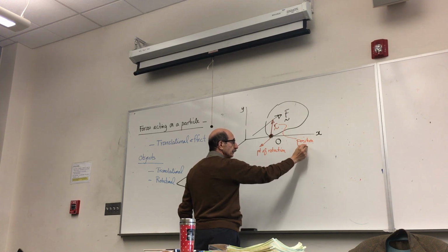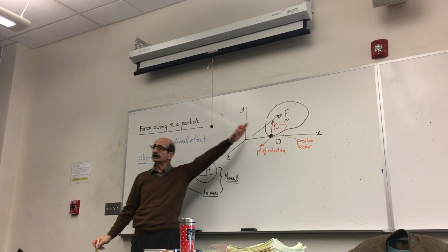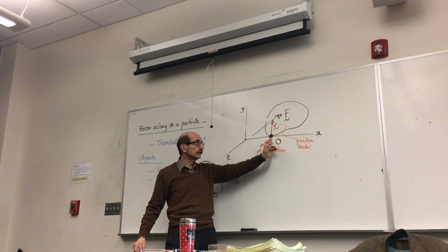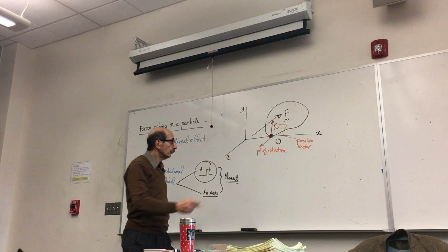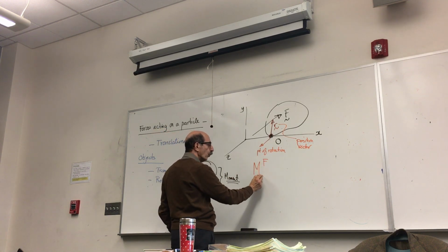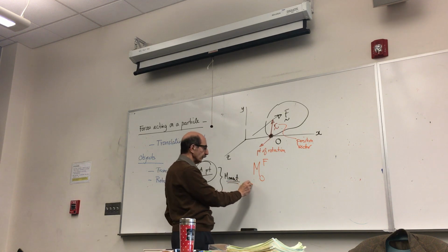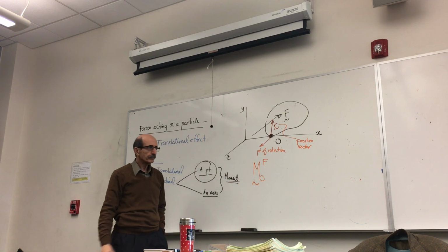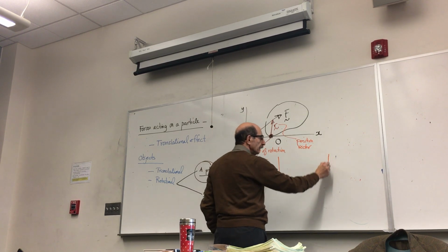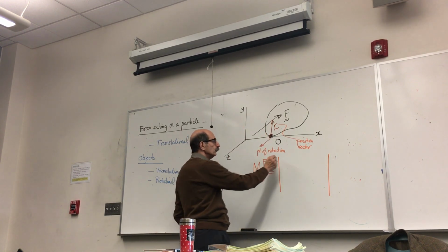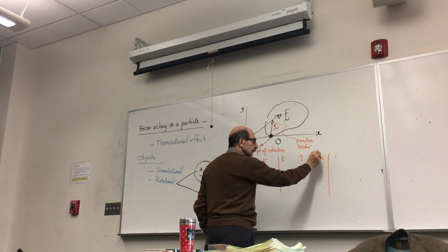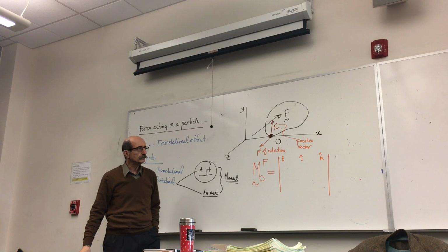It is a vector that describes the position of that force about the point of rotation. The moment of this force about a point, which we write this way, is a vector that is found by setting up a determinant whose first row are the unit vectors of the coordinates.